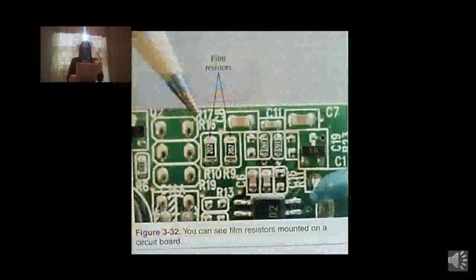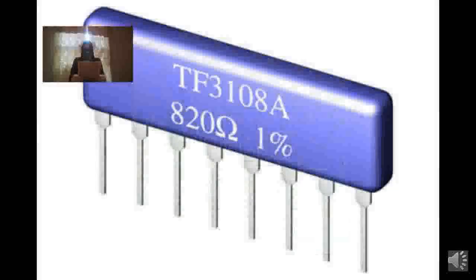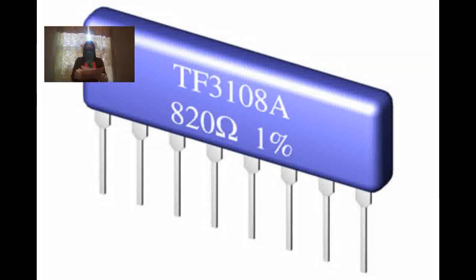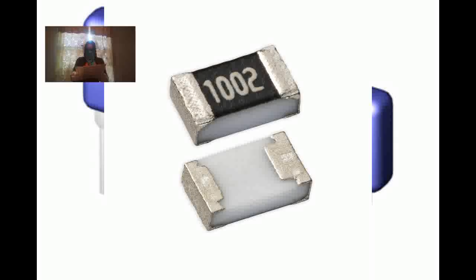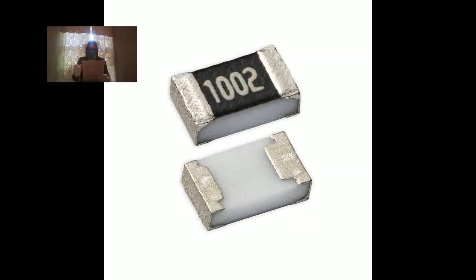As a result, thick film is typically a thicker deposit of resistive material as compared to thin film. The advantage of thick film is the resistor can support higher currents and wattage than the thin film. The advantage of thin film is that smaller components requiring less height can be made.